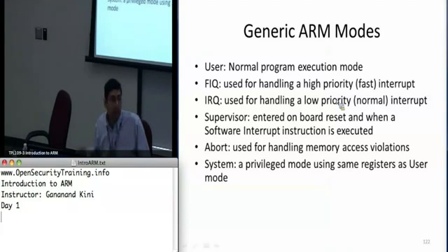And if you look at the vector table, which I'll talk about more later, the way to handle a supervisor mode interrupt, or supervisor exception, is to run the handler that's located in the interrupt vector table for supervisor. All that does is start executing a specific address.